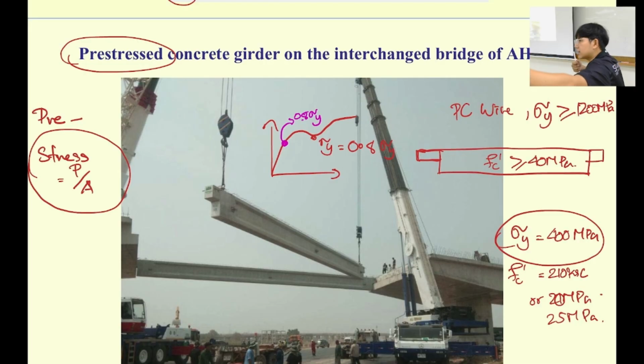So that's when I and him pulling the steel. Okay, when I cut it, what happened? It's similar to loading and unloading that we just talked about. So when it's in the linear region, after I release the load, what happened? The steel trying to go back. So there will be some stress pushing to the surface of the concrete over here.